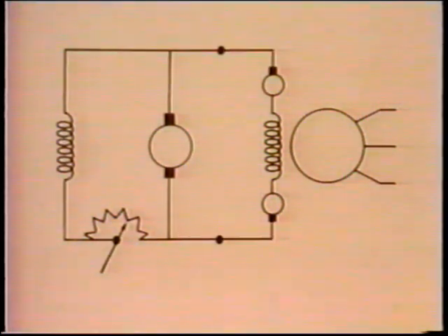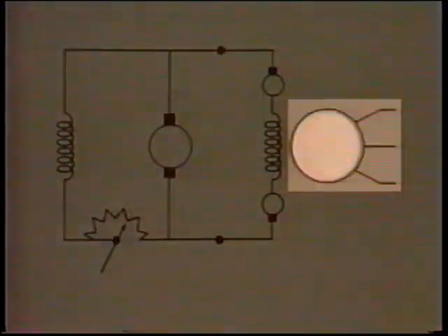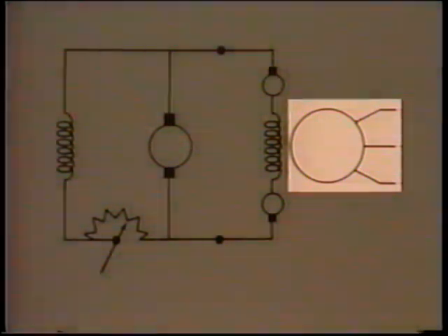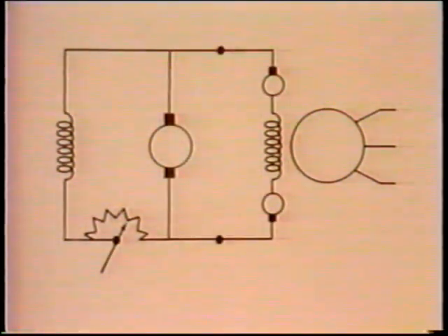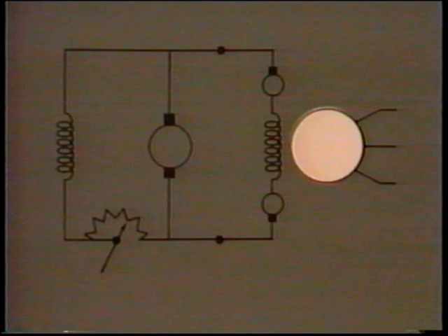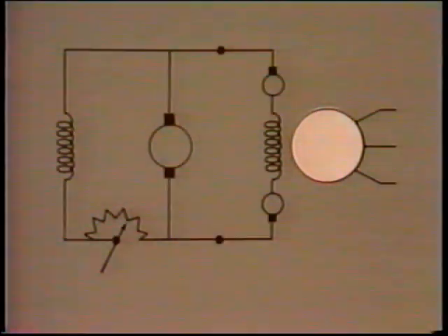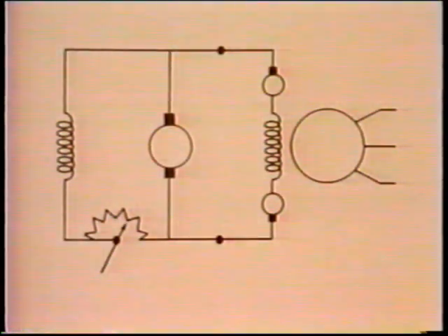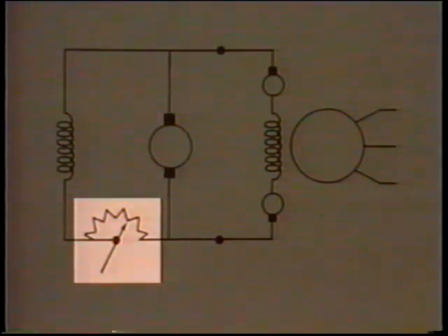Here's the AC generator, its field, its slip rings and brushes, and two leads that connect it to the exciter. Here's the stator, and its three leads. If we rotate the exciter, direct current flows through the AC generator's field. The direct current is the excitation for the AC generator. Now, here's where voltage control comes in. You recall that there's a field control rheostat in the exciter. We can increase or decrease the AC generator's output voltage by moving this rheostat.